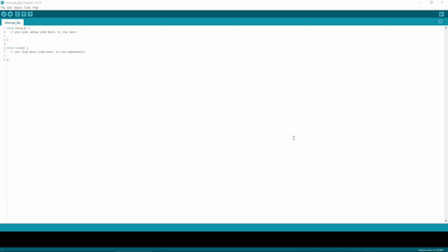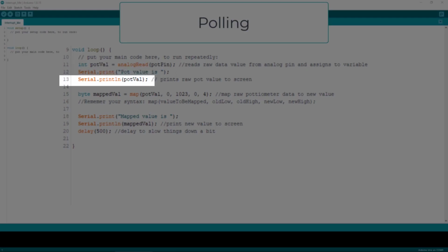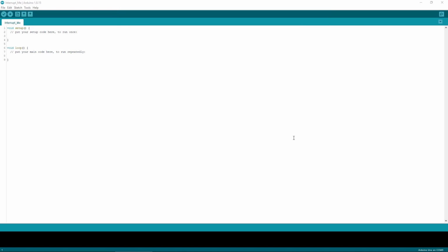So now we know what an interrupt is, let's talk a bit about what we've been doing in our code until now. What we've been doing is polling, or going through and executing each line of code in order. So, if we were polling a sensor, that simply means that the code checks it over and over again every so often to see if anything has triggered it. This would be analogous to your getting up every minute to make sure the toaster hasn't caught fire. Yeah, it works, but it's inefficient, and what if you're 30 seconds late? Then you have an even bigger fire to deal with.